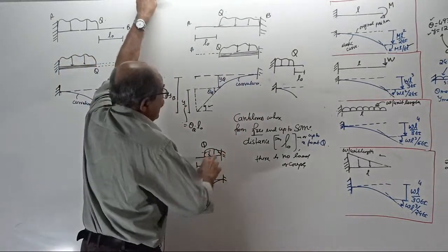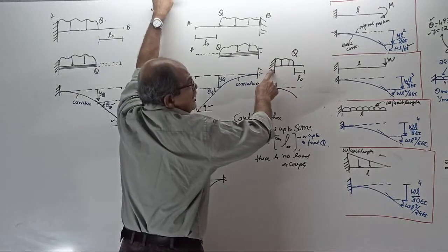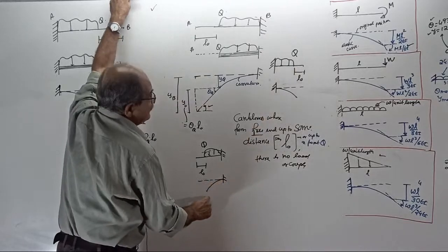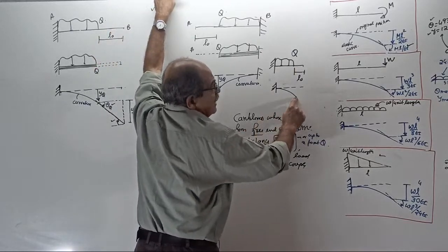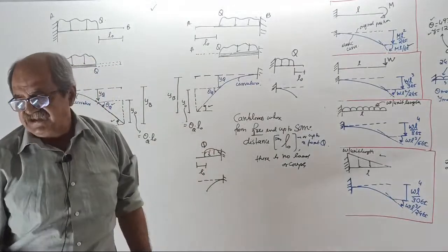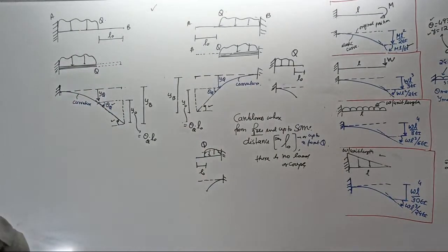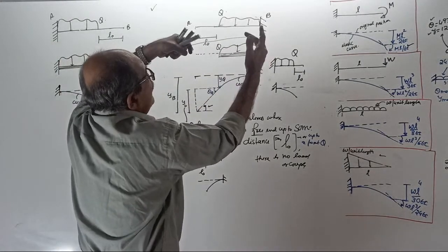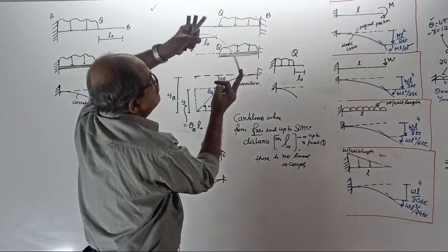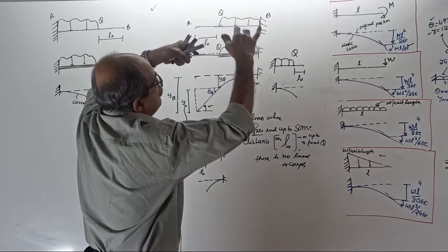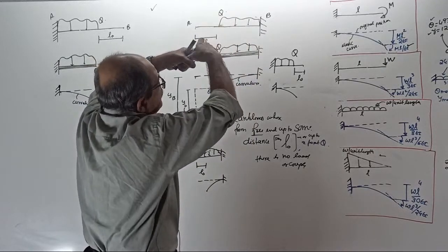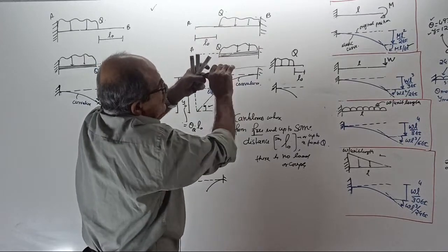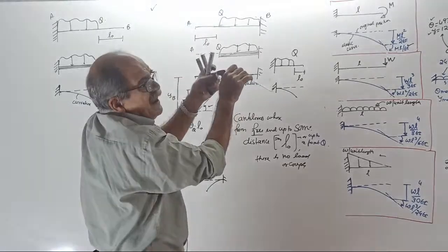Then when the beam bends from the fixed end, the elastic curve comes this way, here like this. Once you reach here, then onwards, tell how the elastic curve is. You can tell it is straight. If I apply a load at the free end, the full beam has curvature. Now if I apply a load somewhere here, this portion will bend. The remaining portion will not bend.